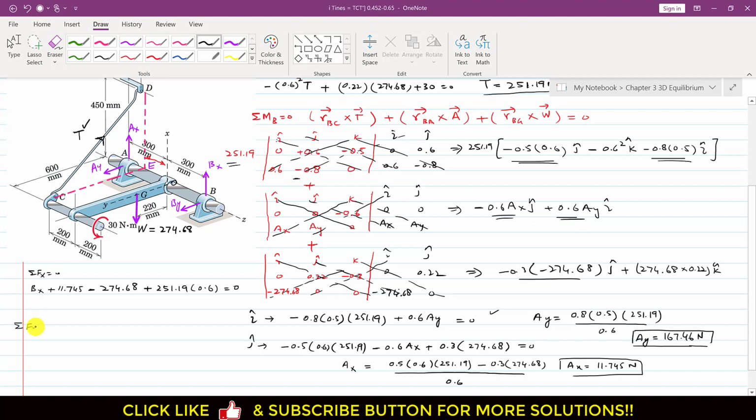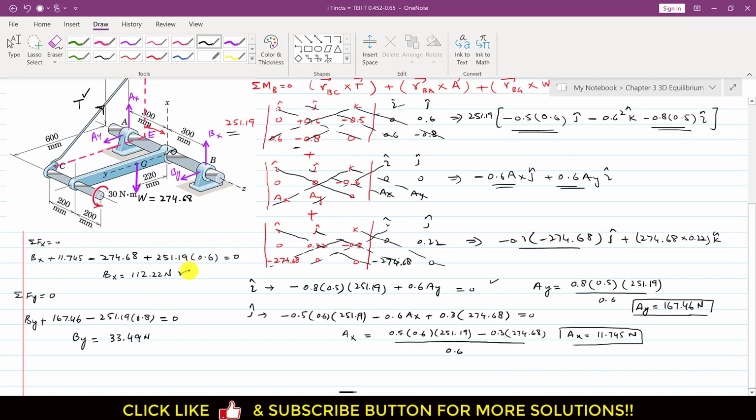And now if we apply another equilibrium condition, that is the summation of forces along Y equals to 0, we can write that this will be BY and then plus this AY, so AY is again known, which is 167.46, and then there is another component of this T which is acting in the negative Y, right? So that component is 251.19 into minus 0.8, right? So we will write minus 251.19 into 0.8, and this will be equal to 0. Now when we solve this equation, Bx is 112.22 Newton and By is 33.49 Newton.